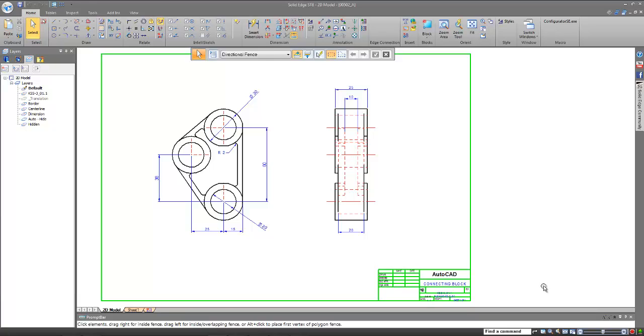to the existing 3D model. So we saw before when I open up a 3D model that came from another CAD system, again it's just a simple body feature with no intelligence unless we go through and manually apply that. You saw earlier how we went through, opened up the 3D model of this housing component, and added the dimensions that we wanted manually. What we could do is take the manufacturing information off of this 2D drawing and place it on the 3D model automatically, this is how we do that.